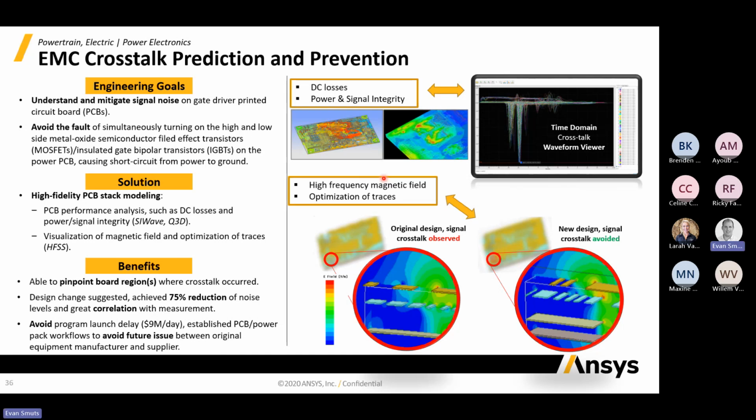And then if we want to work more in a 3D space, obviously PCB is very planar. Some people talk about it as a 2.5D space because it's essentially layers of a board. The layers are 2D and then you just kind of stack them. But if we want to get into more of a 3D type model, we can then use HFSS to look at the full 3D field values. Okay, and in that case, we can even then parameterize things like the trace dimensions, so we can actually do a parametric study, an optimization study on their size and layout, and understand what their effect is on the 3D field from there.